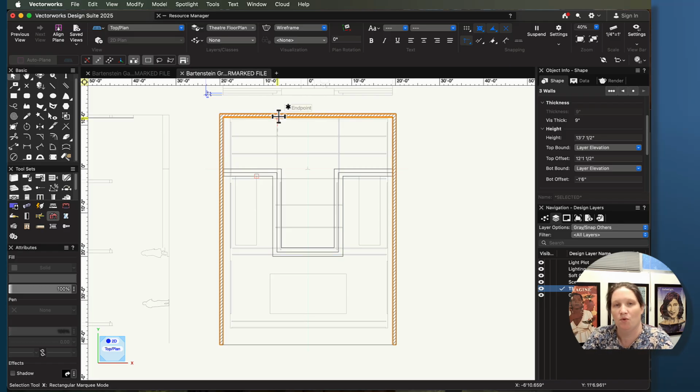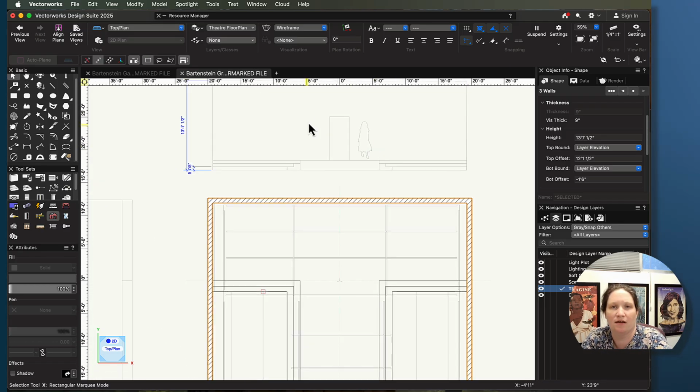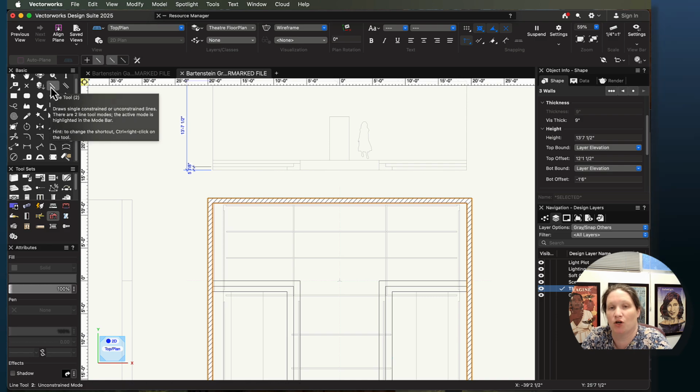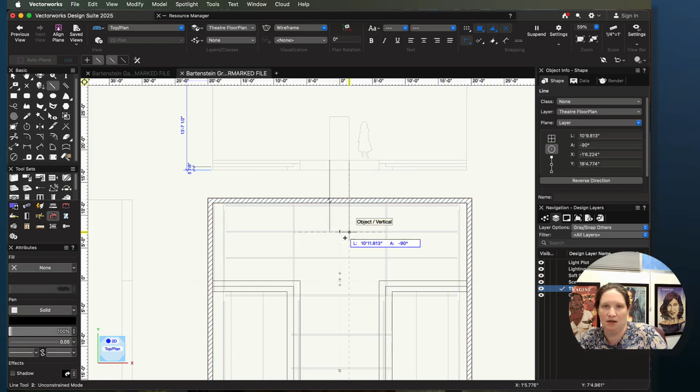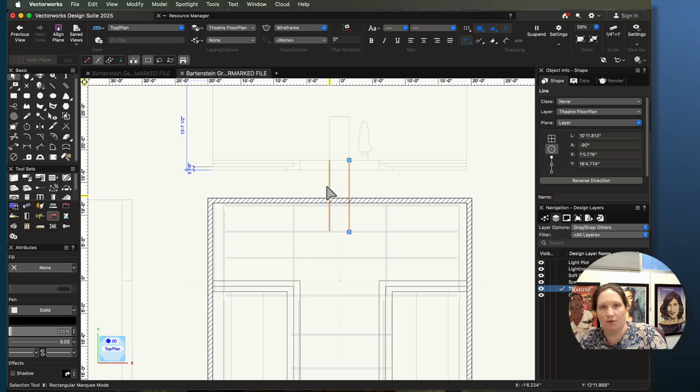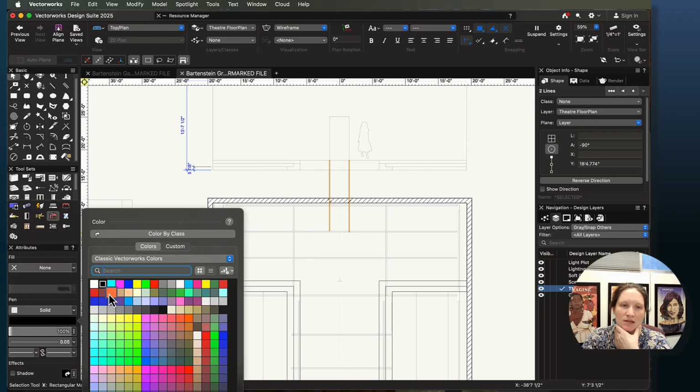So we have a stage, we have a wall. It looks like there's a door centered here in the back. However, it does not appear in the ground plan, but it should. So let's quickly rough in where that door goes, and then we'll use the door tool to actually put it into the stage. So I'm going to just pick up my line tool. This is a good opportunity to get a fun line color, right? I'm going to hold shift, and I'm going to just trace down from that door to where it would intersect with the existing wall I just created.